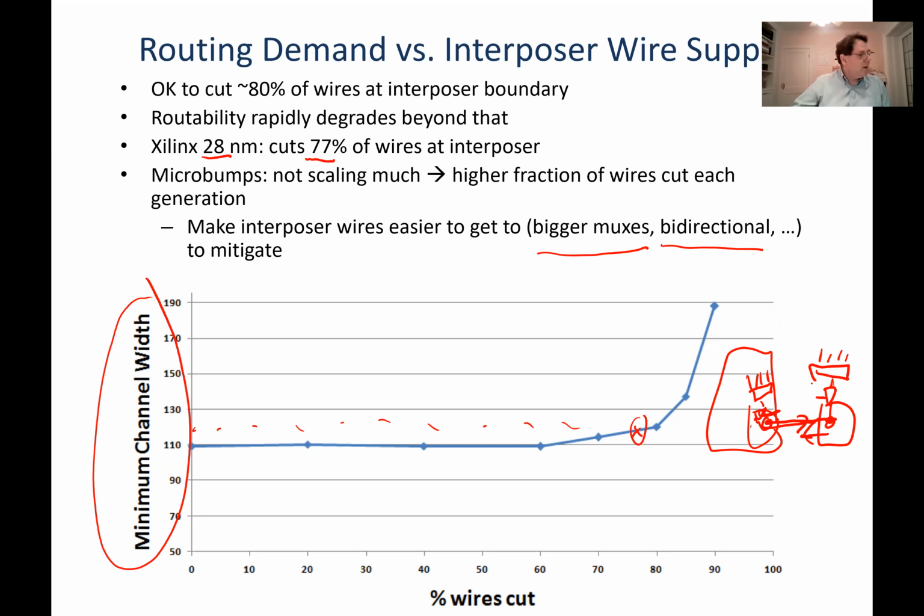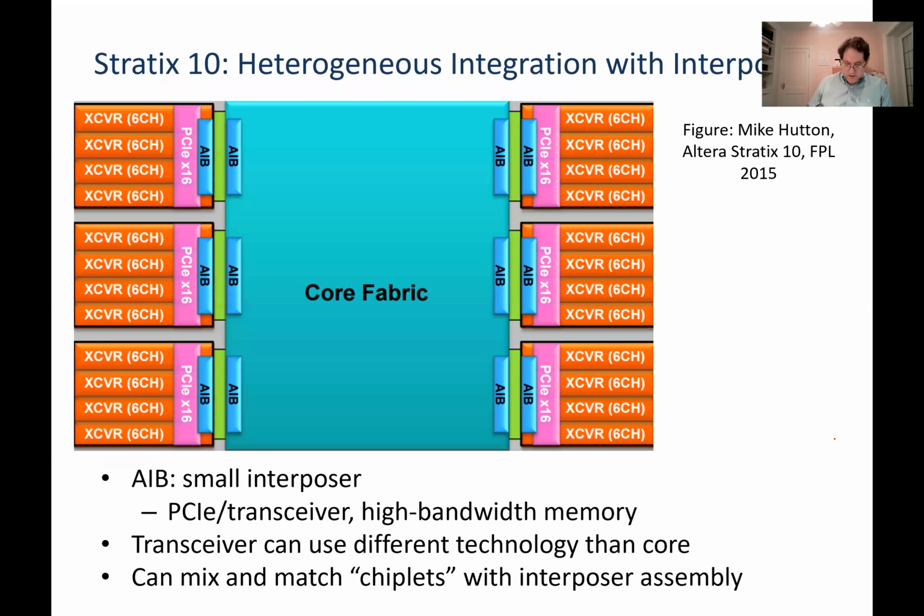So it's a case where tri-state buffers are still very useful because the wire is so expensive. We don't want to use a direct drive switch where we can't tri-state the driver on this wire, because the wire is rare and expensive. Okay, so that was Xilinx.